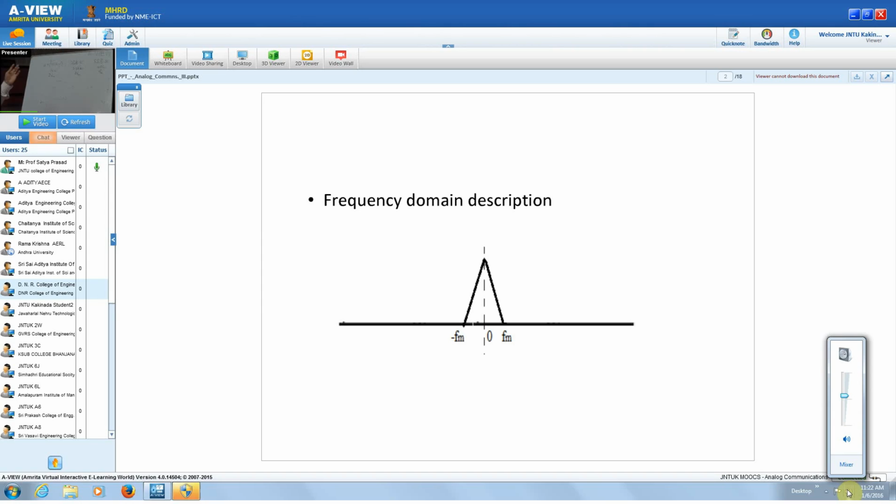Carrier. So we are using here for DSB-SC and SSB-SC a coherent carrier. That means in the case of AM, the detection is a simple rectifier detector or envelope detector. A simple diode and resistor capacitor combination is enough to identify the envelope if the modulation index is less than 100%. So we are able to obtain the envelope by going for a simple envelope detector for this AM.